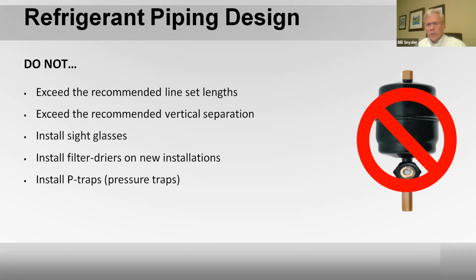We don't install sight glasses because we do not have a true liquid line. If we install the sight glass, you would always see bubbles in there. Even if you drastically overcharged it, you'd always see bubbles in there. So a sight glass will do you no good in this application. So don't put a sight glass on, and don't install filter dryers on new installations.